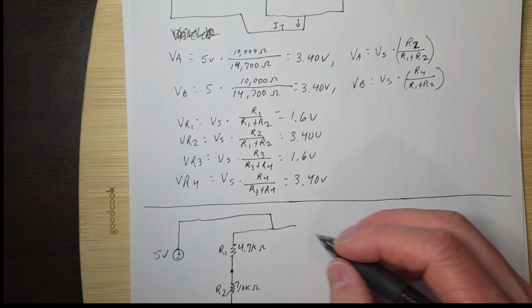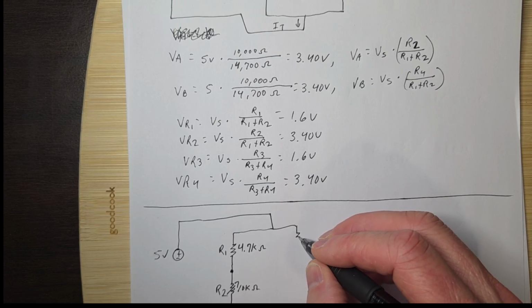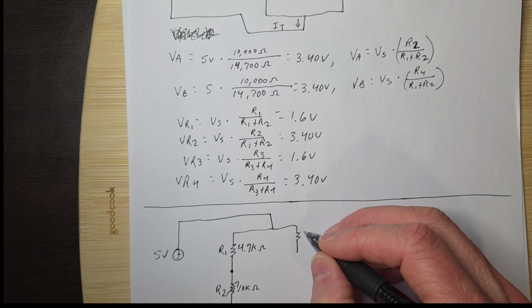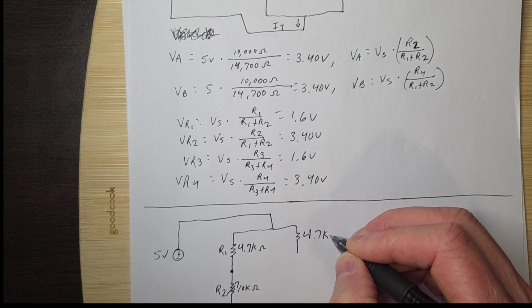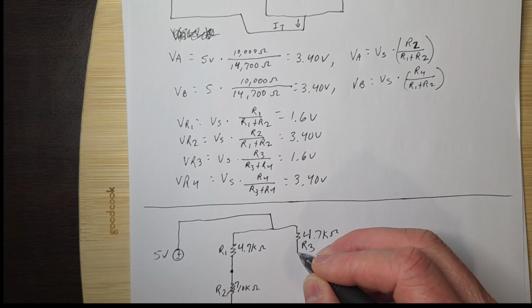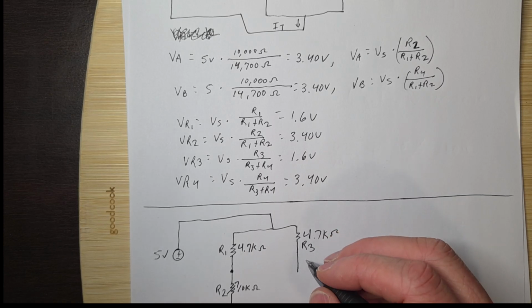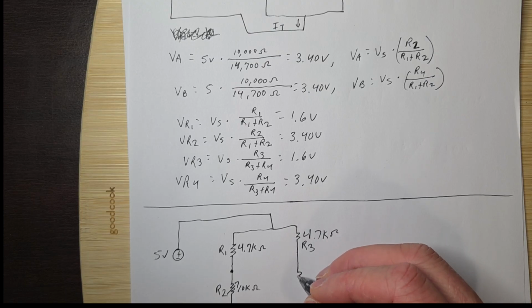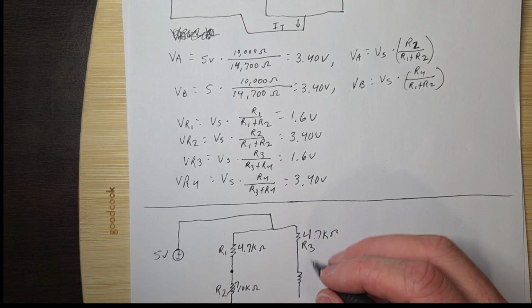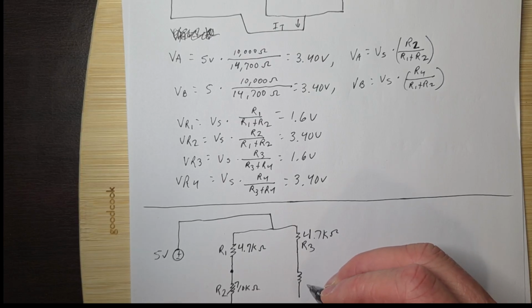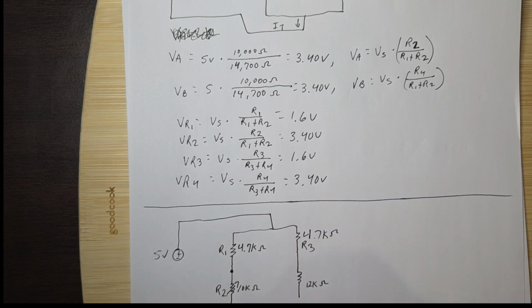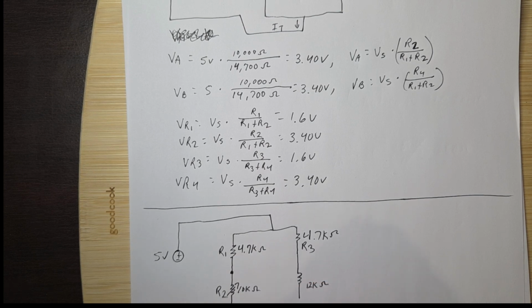potentiometer, and then what we're going to do is we're going to have a, and here in a second I'm going to hopefully not throw you off, because this is R3. Now here's where it gets kind of weird. We have a thermistor, and at room temperature it was about 12K ohms, and our potentiometer only goes up to 10K ohms. So what I'm going to do is add in another 4.7K ohm resistor here, and I know this looks really weird,